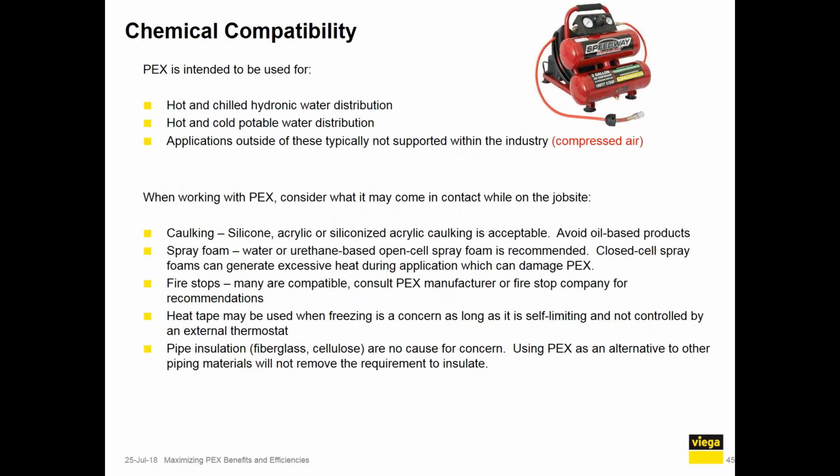Chemical compatibility. PEX is intended to be used for hot and chilled hydronic water distribution as well as hot and cold potable water applications. One way that it's not supported is compressed air. This is an application outside of what's typically supported.